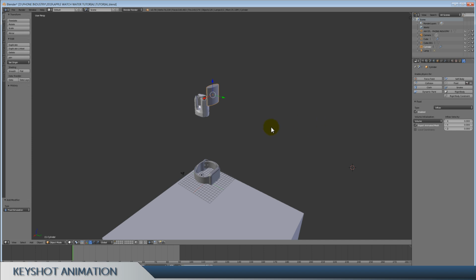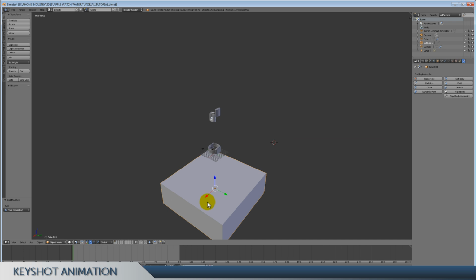So after switching and making a couple of iterations, I came to the conclusion that for this one speed should be somewhere around, so on the z-axis we type minus 0.05. You will see later if you like that speed or you want to change it. For now, let's keep it that way. And I think that this cylinder inflow object is pretty much done, and we can go back to our main cube. Actually, let's dive into this second cube that is our outflow object.